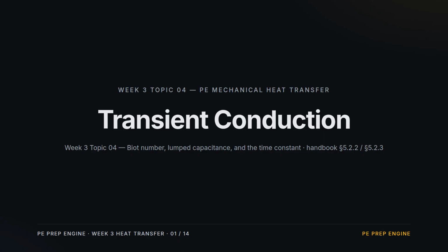Topic 4 of Week 3, Transient Conduction. The Biot number that decides whether you can lump the body's temperature. The lumped-capacitance solution giving exponential decay toward ambient, and the time constant for how fast.